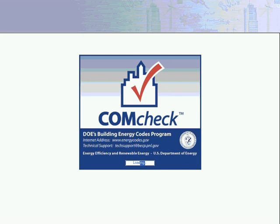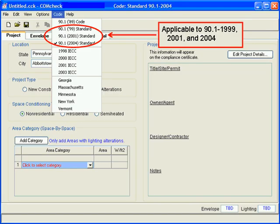Now, the alterations feature in COMcheck is only applicable to certain 90.1 standards. And from the code menu at the top, you'll see in the red circled the ones that are applicable to having this feature allowed. And that is 90.1-1999, 90.1-2001, and 90.1-2004. So if one of those standards is applicable that you can show compliance to within your location, and you can use the alterations feature, then those are the ones that you could use.